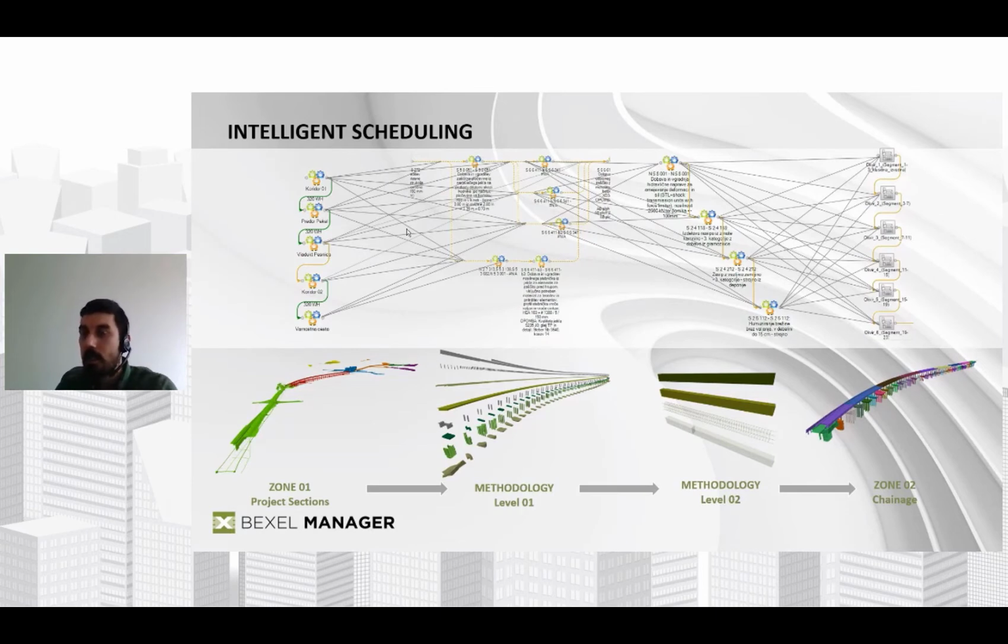The only difference will be that instead of having 2 levels of spatial organization, vertical and horizontal, in this case you're going to have just horizontal spatial organization, or to be more precise, linear project organization. So you're going to have axis, and you're going to have chainage. You're going to have small steps on this axis of executing the works instead of buildings, levels and zones.